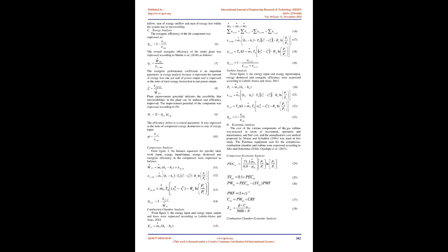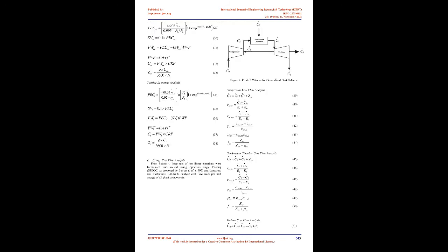Lebele-Alawa and Asuo, 2013, used energy and exergy methods to analyze the performance of a 20 MW gas turbine. Their report shows that the combustion chamber contributes the maximum exergy loss of 38.62%, while the second law efficiency was 16.39%. The components of the power system responsible for irreversibility or lost work were identified for improvement and applied to improve operational performance using the exergy analysis.